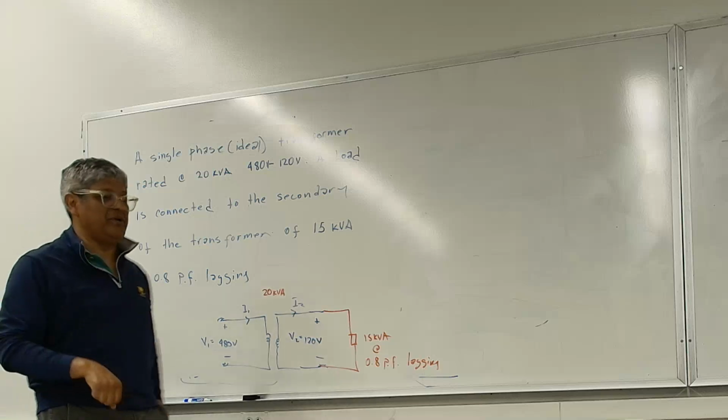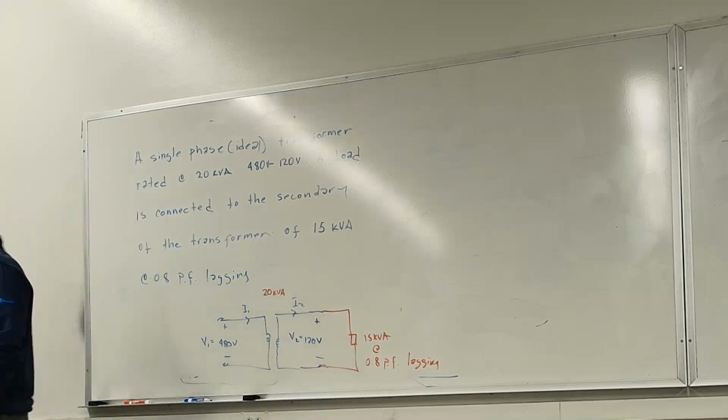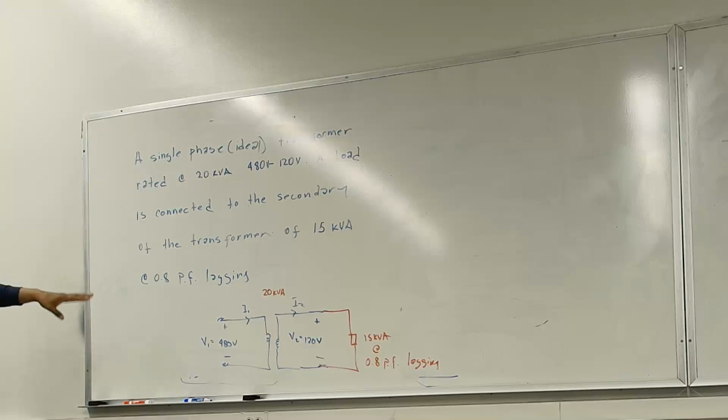The challenge that we have now is that transformers are actually being run either at their rated value or above, and they don't even have a cooling period at night. And why? One of the main reasons is electric vehicles.